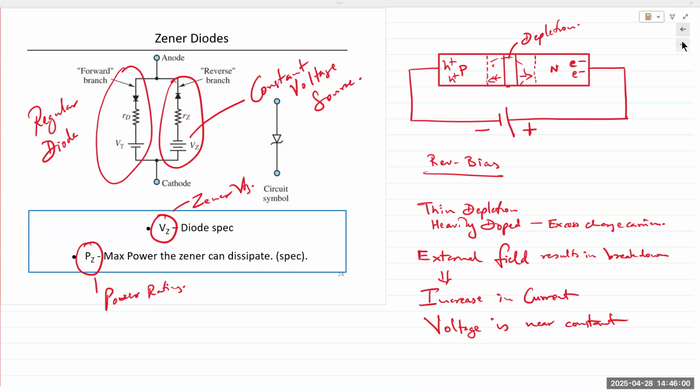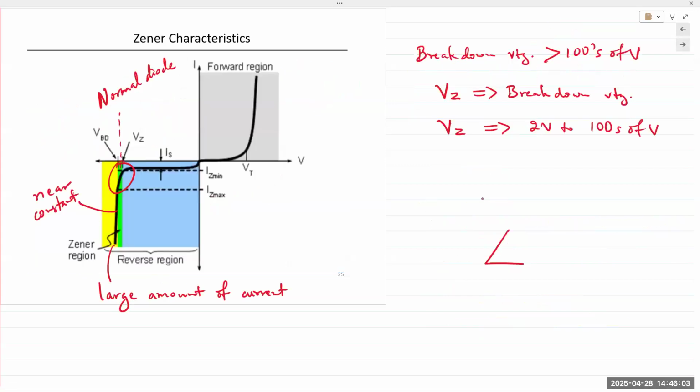Let's talk about the notations. Standard diode symbol, except a Zener diode has whiskers on the cathode. That's the cathode, that's the anode. Diode voltage, VD, is always measured with positive reference at the anode, negative at the cathode. Current flow is always indicated as flowing from anode to cathode. That's ID. That's the normal diode convention.